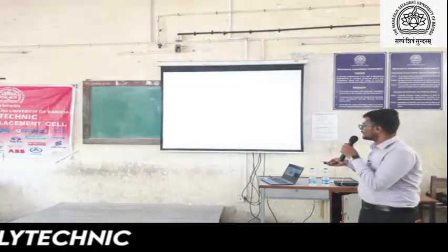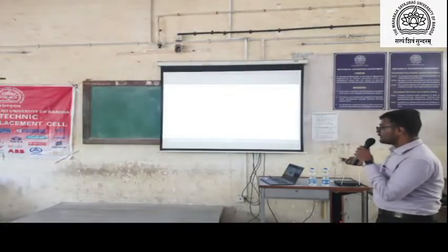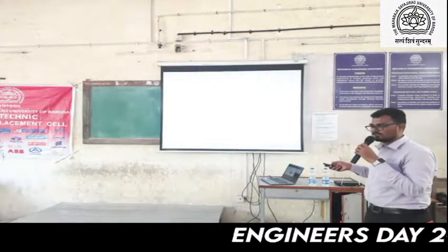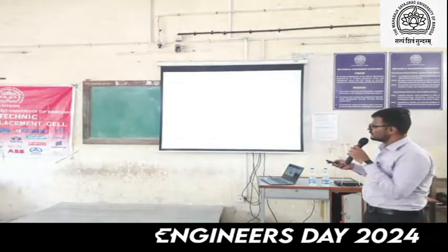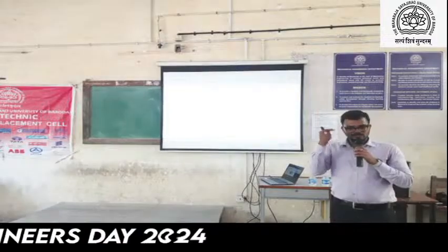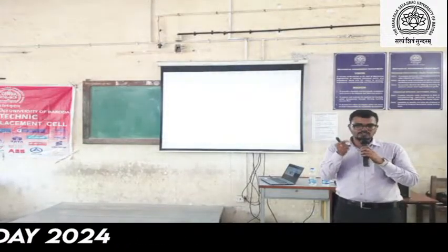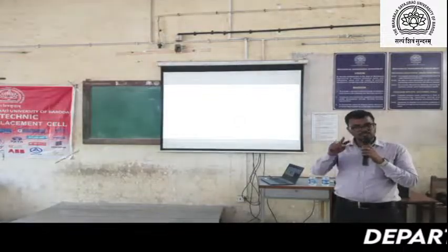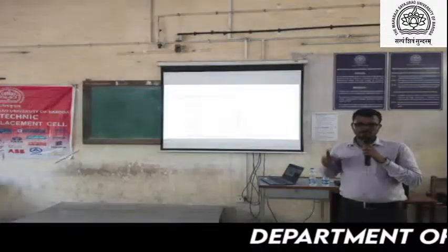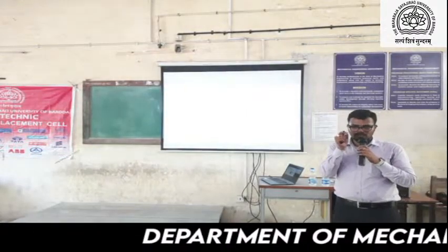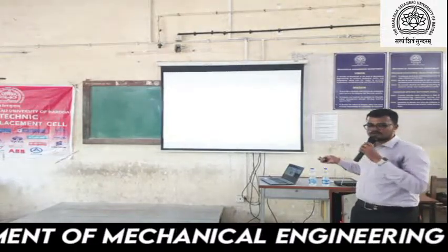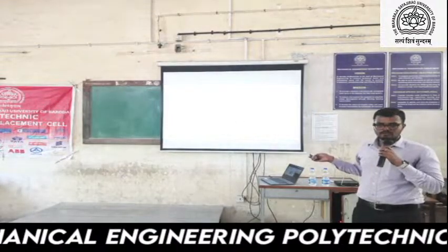So this is the involute profile, this is the cycloidal profile. This is also based on application. Why? Involute profiles will be used in major applications. 98% of gears will be manufactured this way, rotating continuously every day. If it is rotating with an efficiency loss of 1%, think about the effect. So in that kind of high precision, high accuracy application, the cycloidal profile will be used. Am I right?